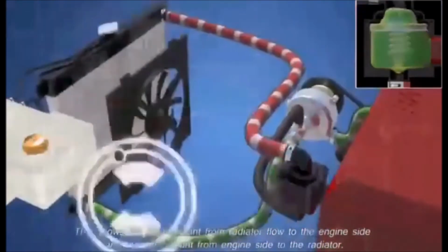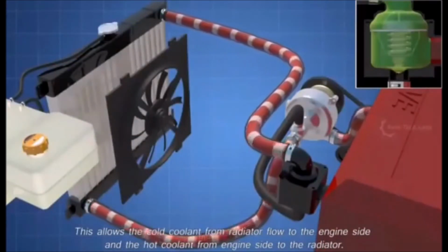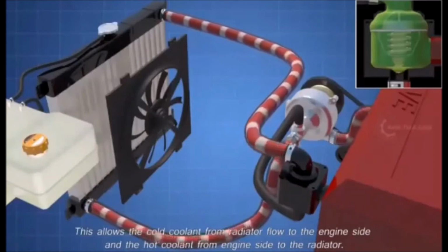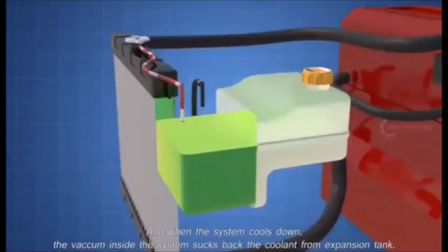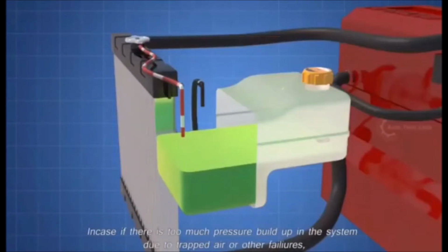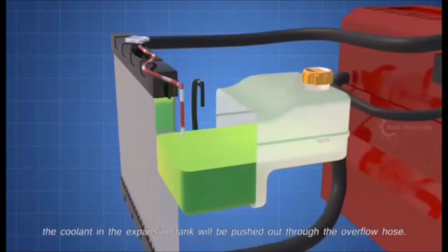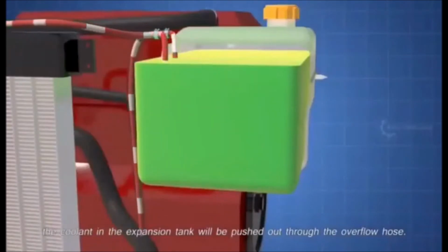This allows the cold coolant from the radiator to flow to the engine side, and the hot coolant from the engine side to flow to the radiator. In most cars, the system sucks back the coolant from the expansion tank. In case there is too much pressure build-up in the system, due to trapped air or other failures, the coolant in the expansion tank will be pushed out through the overflow hose.